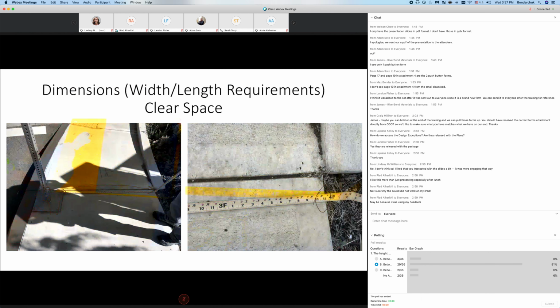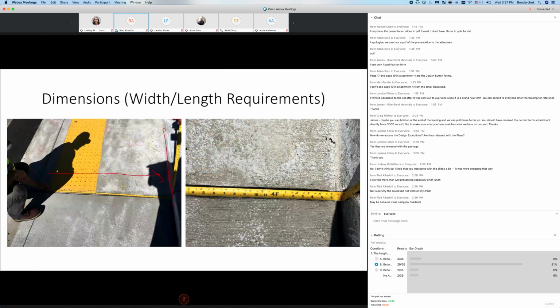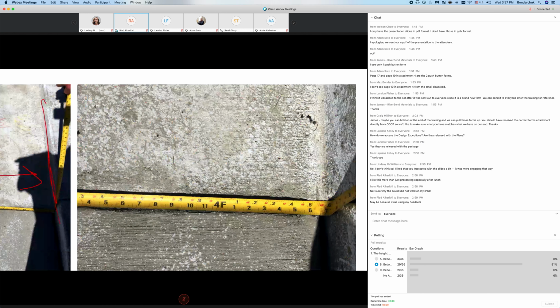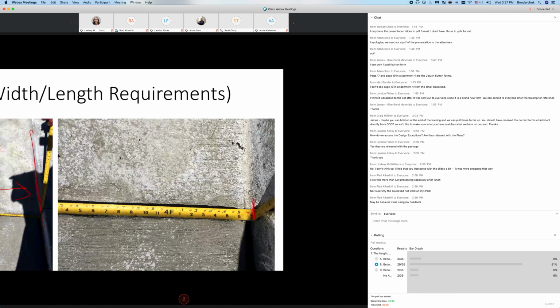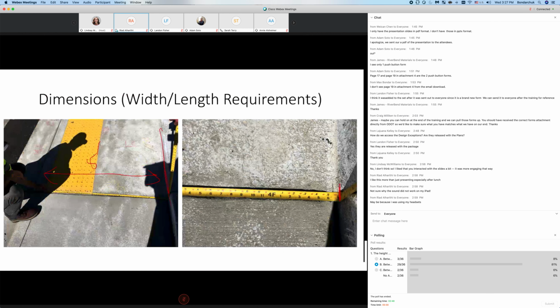Dimensions again, if you have a back of ramp obstruction, this length should be 5 feet. And here you can see we are about 4 feet 7 inches. It feels so sad that you get all this concrete poured and you have to remove it, just from not paying attention to getting to this dimension exactly. That's why you check forms and check drawings before you get there.